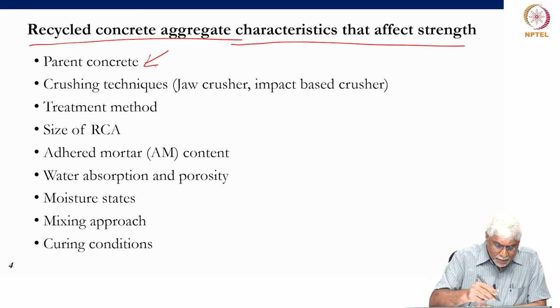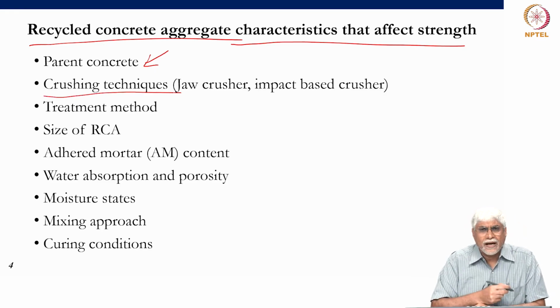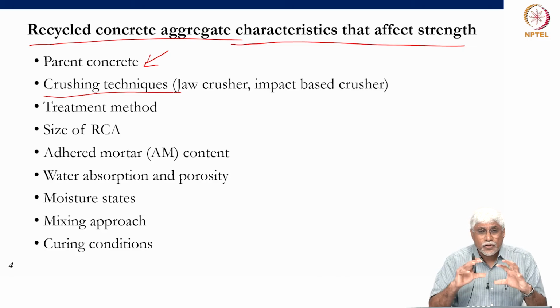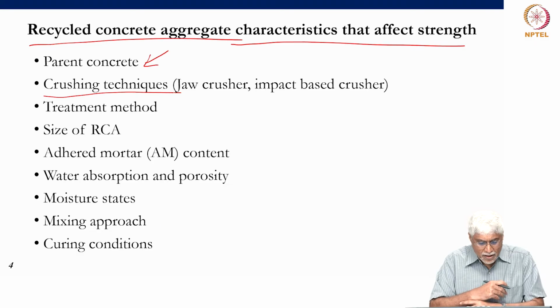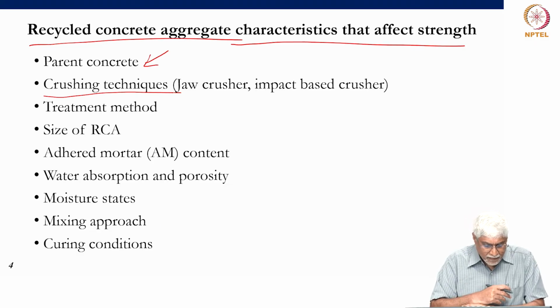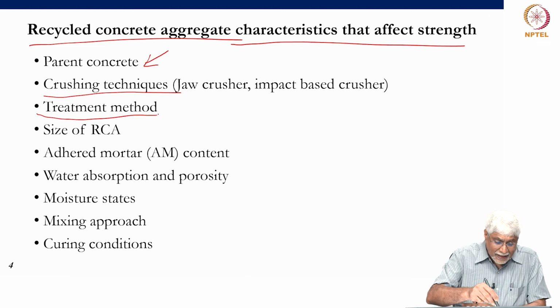How we crush matters, because some crushers are more effective in removing the adhered mortar, in making sure that we have reasonably rounded size particles. So, that is being covered in other lectures of this module. Do we do any treatment afterwards?